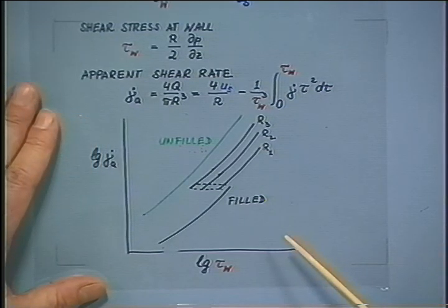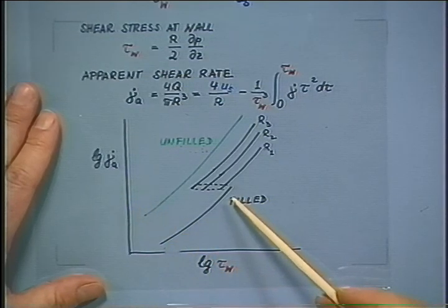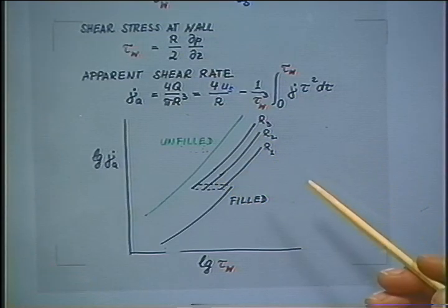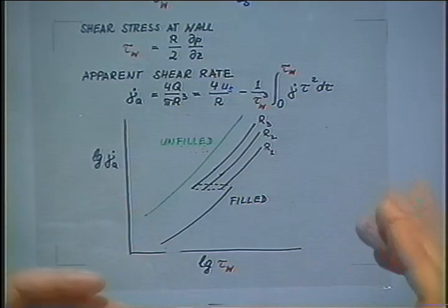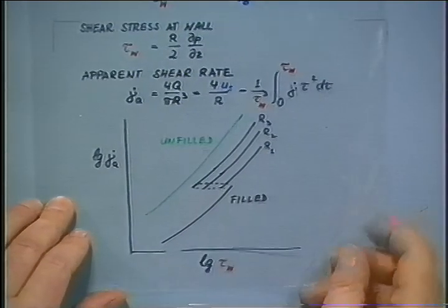Now, we measured the pressure drop flow rate relation for a filled system. And there you see a strong radius dependence. As soon as the liquid starts to slip, there is a contribution to the throughput, and you see that in the experiment very nicely.